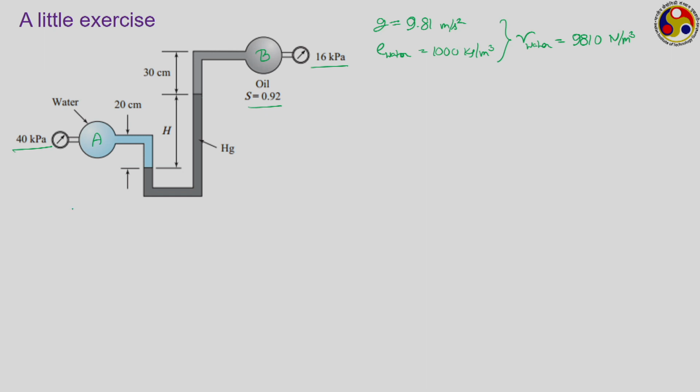So, what is the common choice of plane? This one looks like to be the most common choice, because below this one you are having just single fluid. We generally always go by choosing a plane below which we have just single fluid, a continuous span of one particular fluid. So, we can neglect the below portion from the calculation.